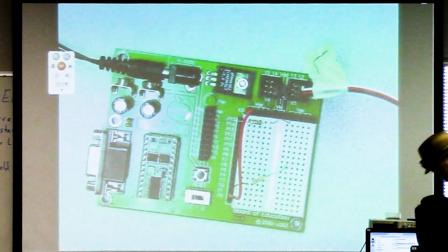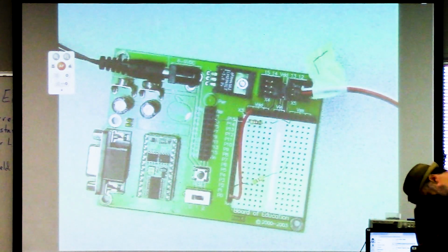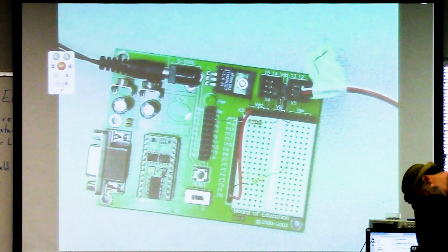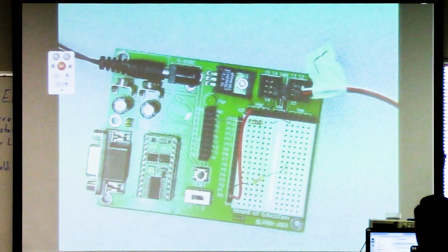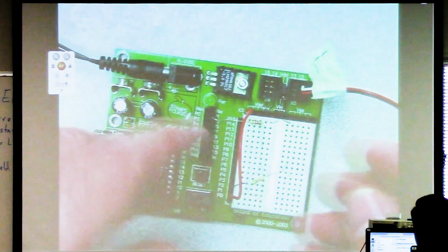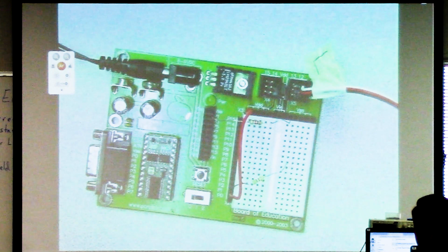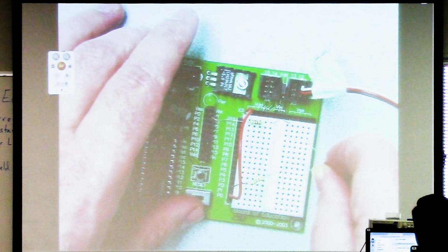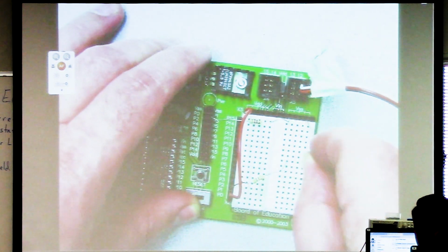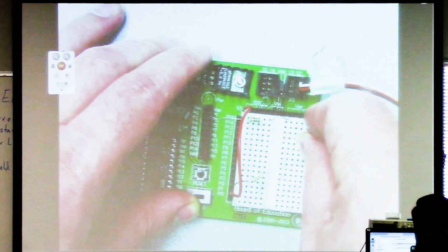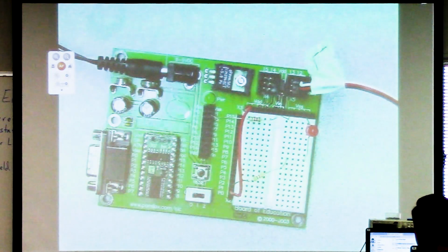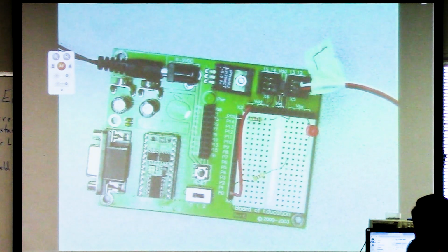And then we'll get an LED. And that'll go from this resistor down to VSS. And again, remember that LEDs are polarized, so you need to have the flat side of the case going towards VSS. All right, so that should be our circuit there.